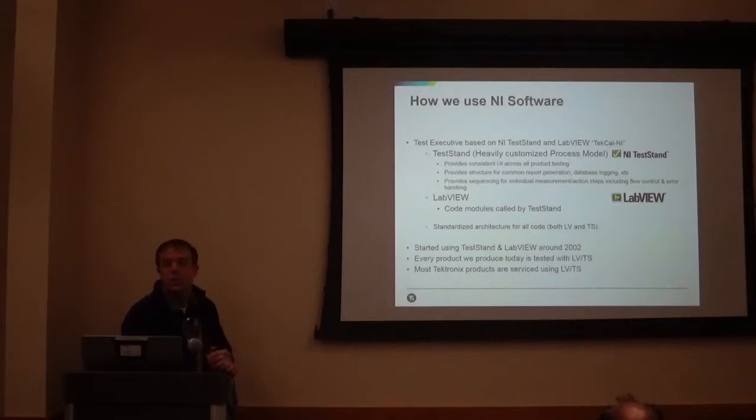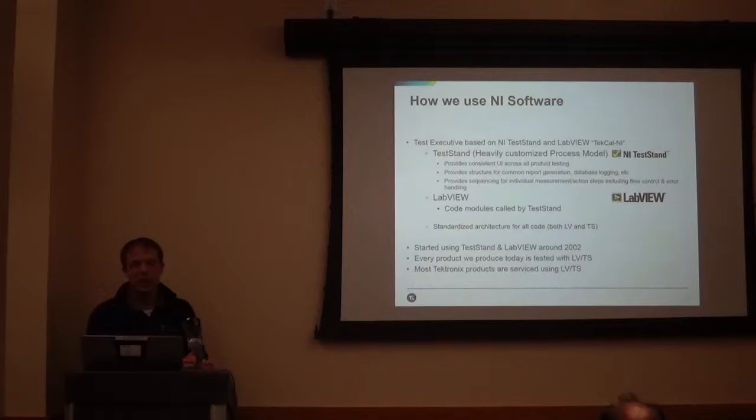How we use NI software at Tektronix: we have an internal test executive based off of National Instruments TestStand and LabVIEW. We term it TekCal NI. It's based off of TestStand, with a very heavily customized process model that provides a consistent UI across all of our products for testing, and common report generation and database logging. All that is the same in every factory, every station around the world.